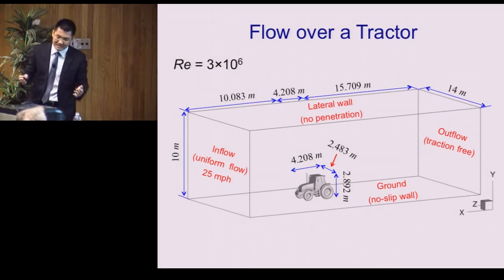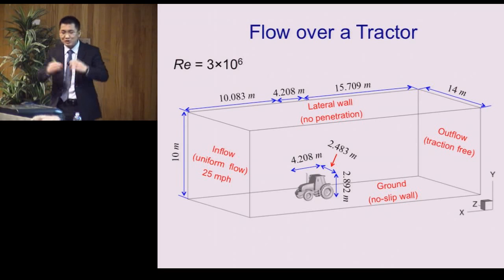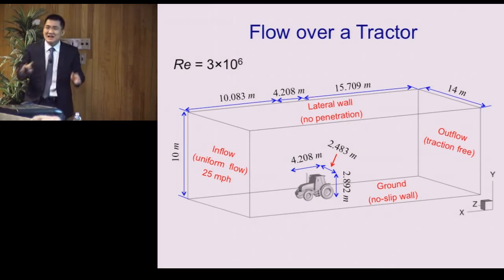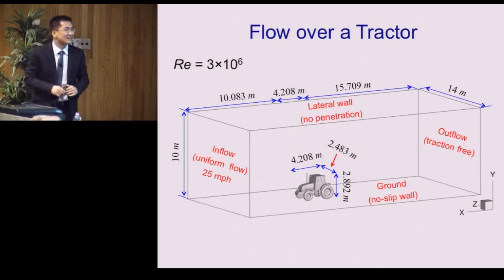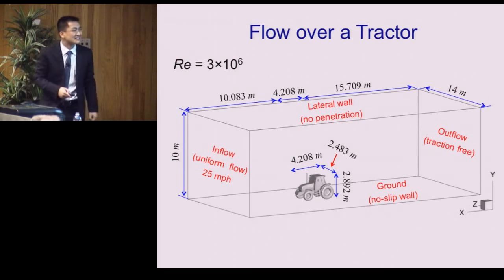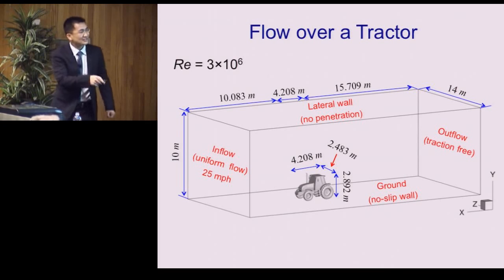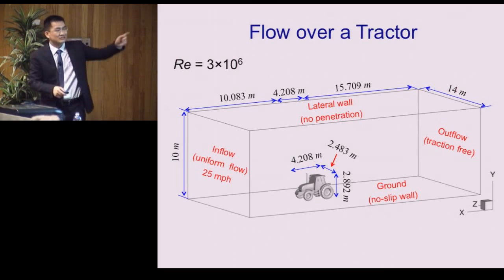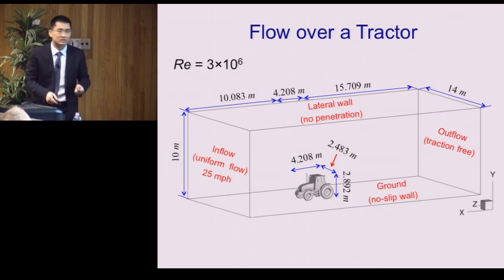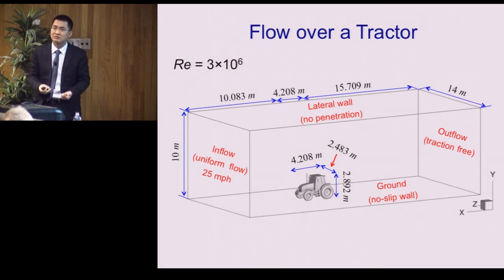I was presenting all these ideas of isogeometric analysis, integrating the design and analysis. And he said, well, I honestly don't really care about that, because what happened to us is that to do a CFD analysis, it took us about 3 months to be able to mesh the surrounding flow field of the tractor because of all these detailed features they want to model. It is so difficult, so challenging to clean up the geometry, then to match the surrounding flow field.